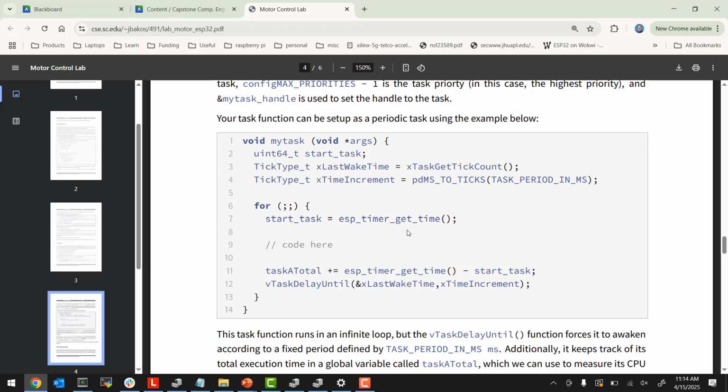Real-time operating systems aren't like Linux where you log in and you get a prompt. A real-time operating system is really just a runtime library. There's no interactivity. You compile it. So FreeRTOS is compiled every time you change your code. You compile the entire operating system. And when you do that, you can put hooks in, meaning callback functions that you provide, that it calls when certain things happen. But Arduino's like, no, not happening. Won't let you do that. I tried. But there's an easy workaround.